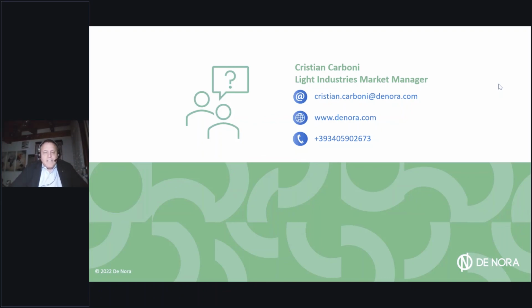Normally, when I talk about the pulse application, for example, we put ozone at 2 ppm for 24 hours, making continual injection of ozone to stay at 2 ppm for 24 hours, and after that we let the ozone decay.